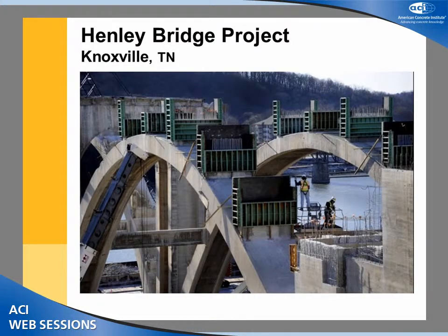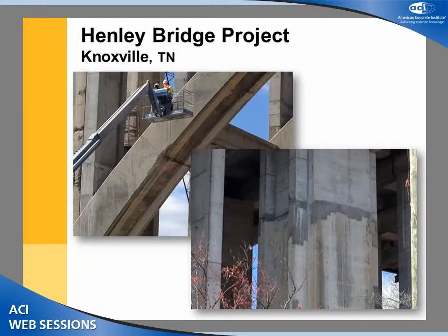And if you look at the activity, the top deck has been taken off, and they're doing a lot of repairs on this project. We can zoom in on the repaired section right here. This has all been done with a prepackaged SCC. Now, if you compare this to a conventional new construction application, an SCC would be a perfect product for this. So when you go out and fix these applications in concrete, an SCC in a bag also helps you with the same kind of technology.